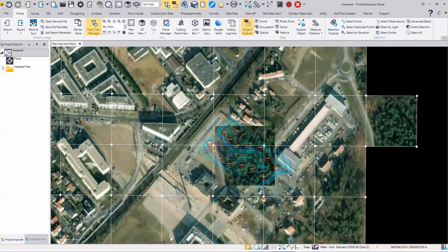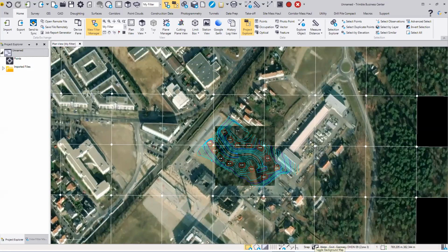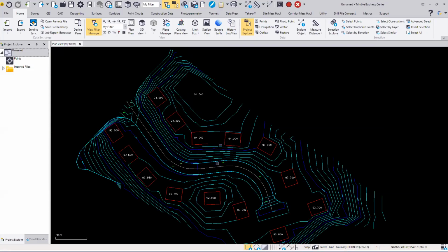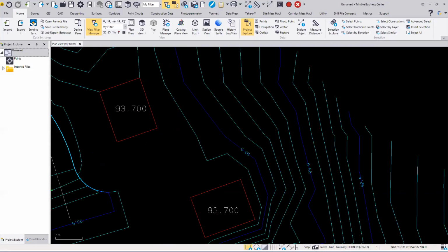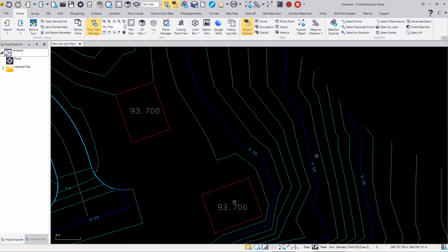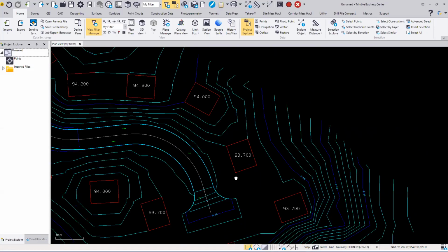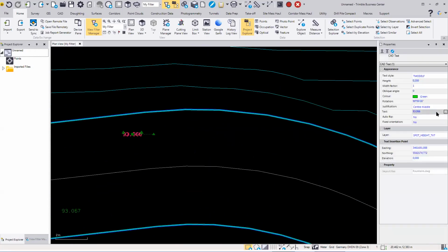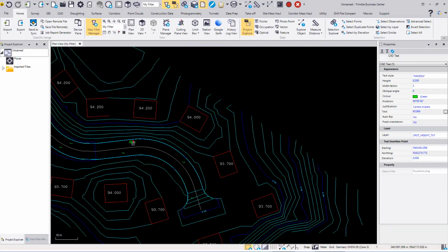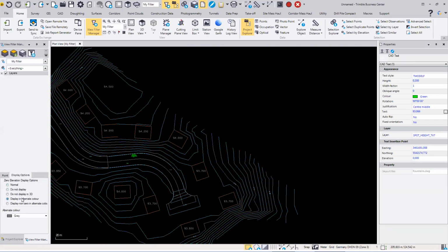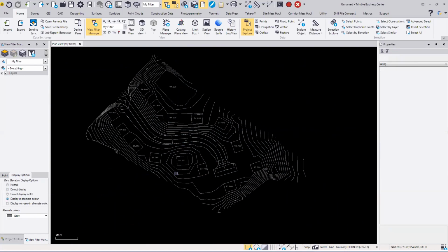But now it is about getting that DWG file into 3D. So what ways do we have to check what kind of file format that is? What we see here is some contour lines with some text elements with elevations, some building pads with elevation. And I see some points, but these are not really points, just text elements. As you can see, text 93.066 without elevation. And the same applies for the lines. So there's a nice display option here, so you can say everything without elevation, display in gray, for example.